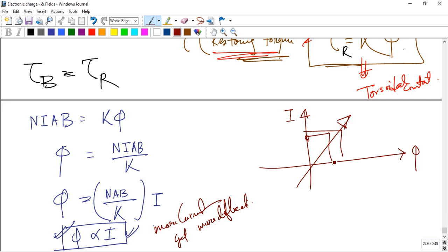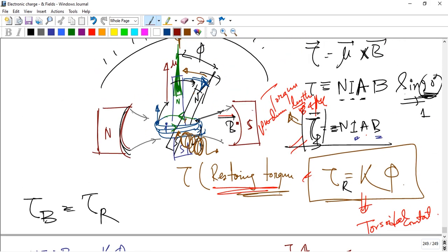Now, this galvanometer is used as a voltmeter, sometimes as a current meter. But there is a certain condition here. This concept we cannot apply directly, because a normal galvanometer cannot measure the current or voltage. The first condition is that a galvanometer is a very sensitive device, with a full-scale deflection in the very small microampere order. And second, a galvanometer has a very large resistance, so it changes the circuit current value.